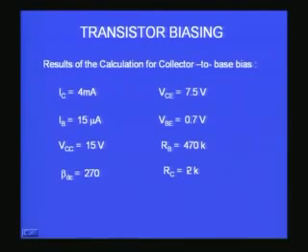So we have now got two different types of biasing circuit. One is the fixed base bias circuit, where I used the VCC itself as a biasing voltage, and I put an RB in series along with the base to provide a constant bias for the transistor. The second circuit is, instead of using VCC, I used the voltage at the collector VC to provide the bias, and so a resistor connecting the collector to the base was responsible for providing the base current.